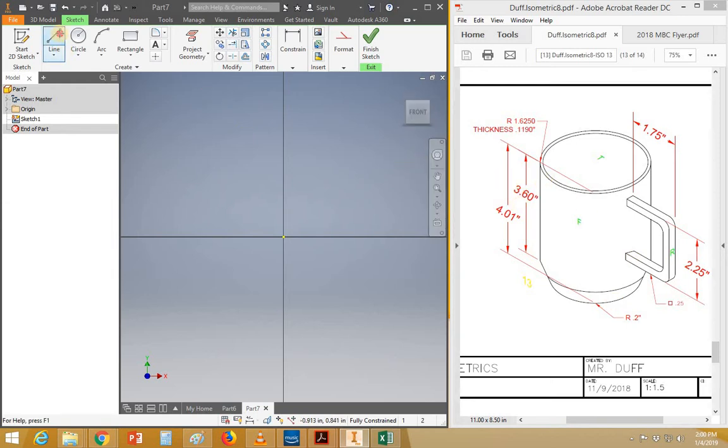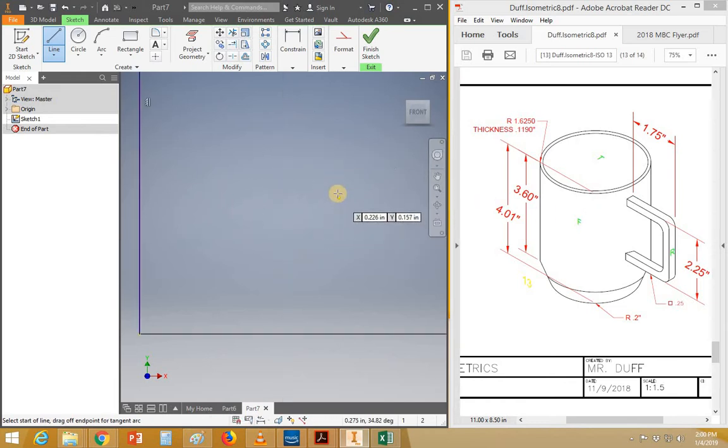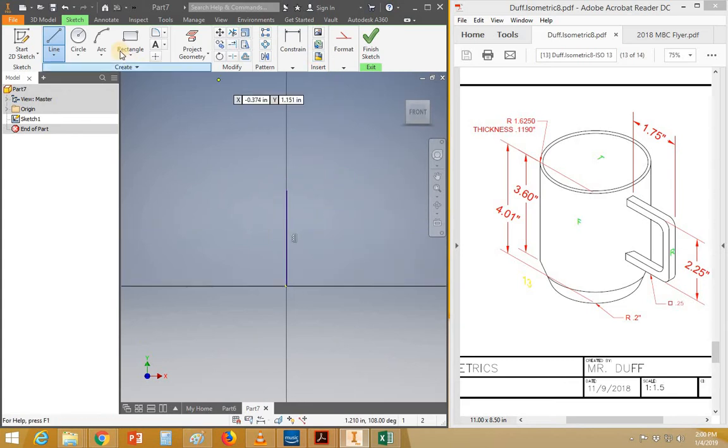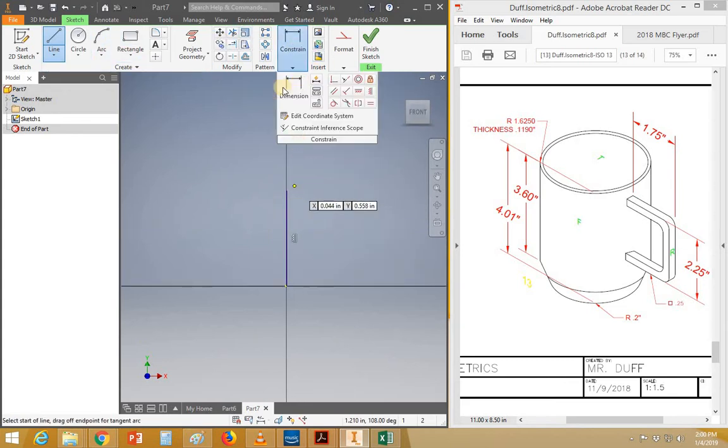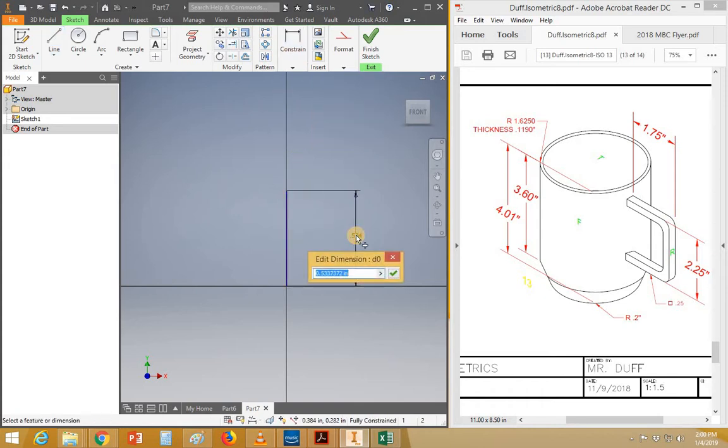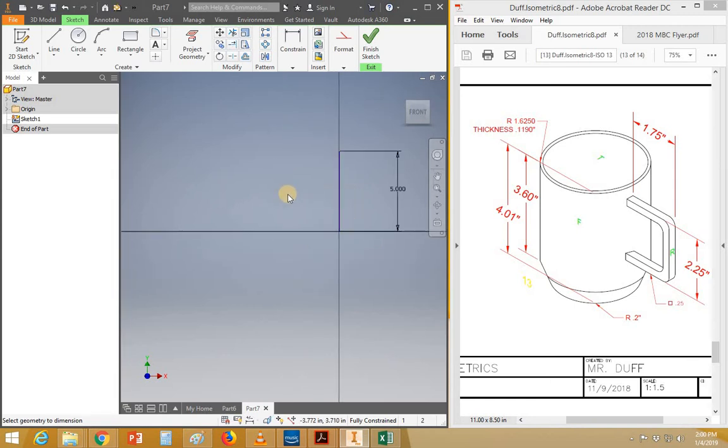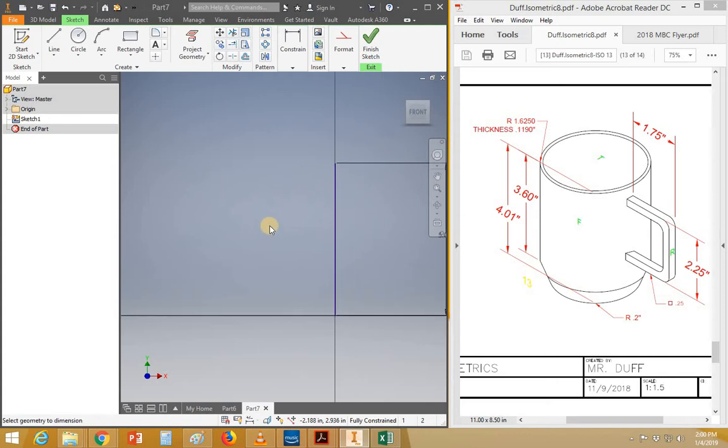So in order to use the Revolve command, you need an axis. So let's put this right from the center point. Okay? And make that axis close to the height. It should be a little bit bigger. So I'm going to dimension it. In general, you should be trying to do that anyway. Make your first drawing so it doesn't get so askew. So the drawing is 4 inches high. Let's just make this line 5 inches, okay? So then we can zoom out and we know that we're drawing things relatively the right size.